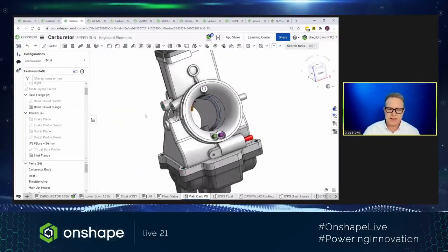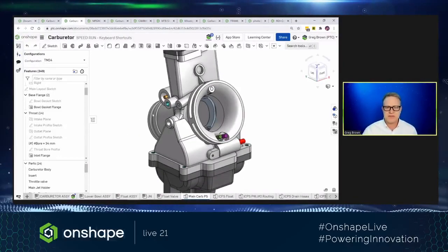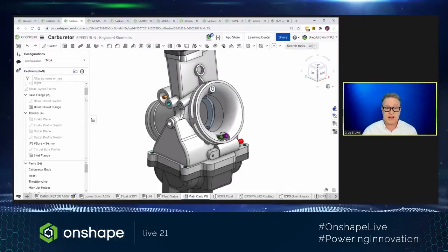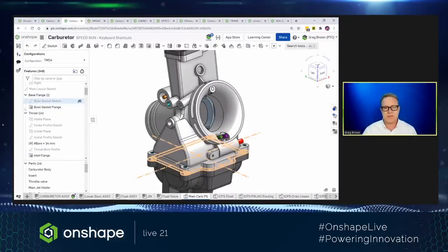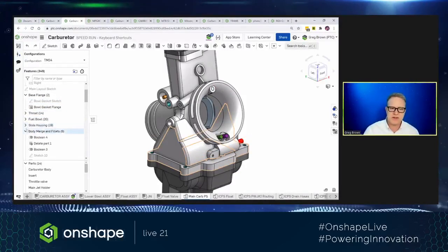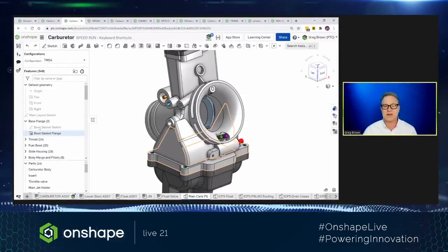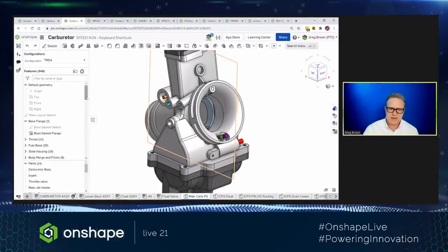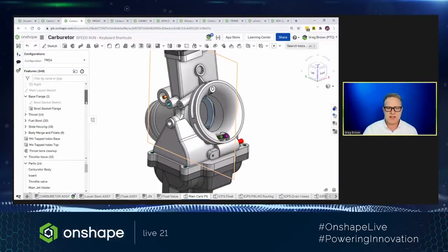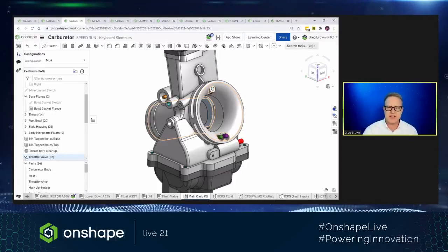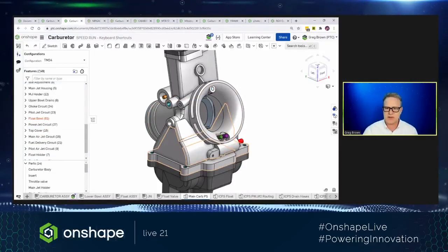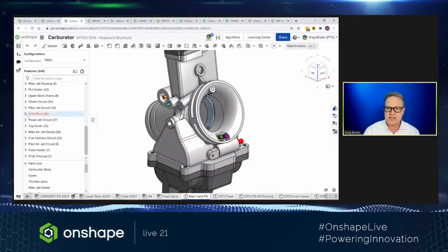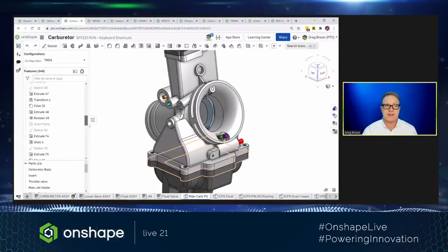Now, going a bit further, the ability to put groups of features into folders, which of course you would properly name, right, really helps keep things neat. This is particularly useful when you have a multi-part studio like this one. I group the features that belong to a specific part together for easy reference. A side benefit is if you have long lists of features in a part studio, like this one has something like 350 features, then you can easily scan down to see if there is a failed feature in any of your folders.